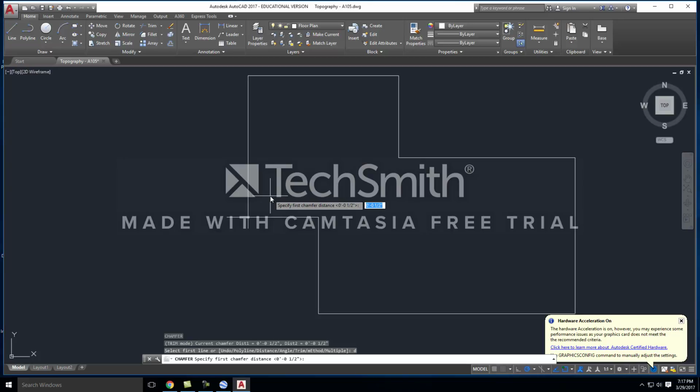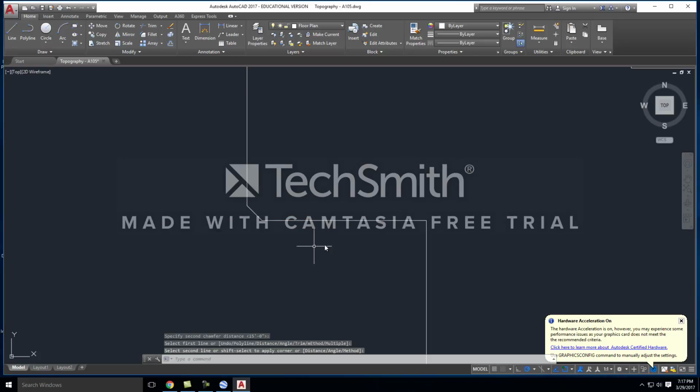Okay, so all you're doing is just changing that angle. But you start to get into some more complicated measures. So again, CHA for chamfer, D for distance. We'll say 15 feet. I'm going to do the same thing for the second chamfer. Then I will select line A and line B, and you get that nice chamfered corner.